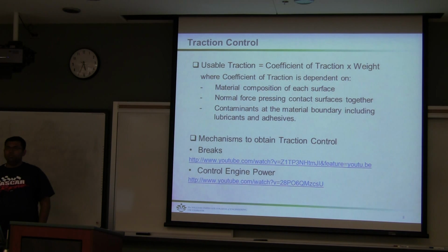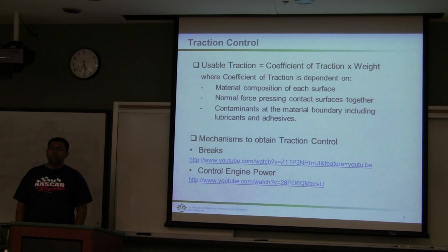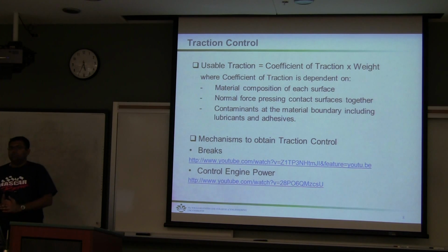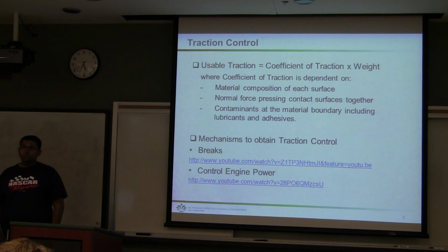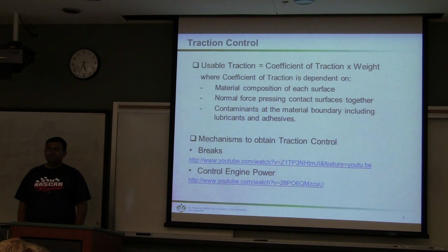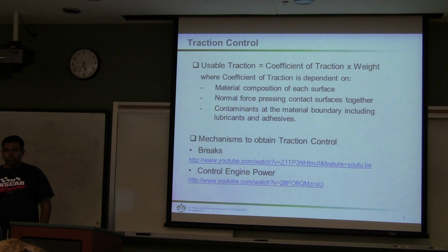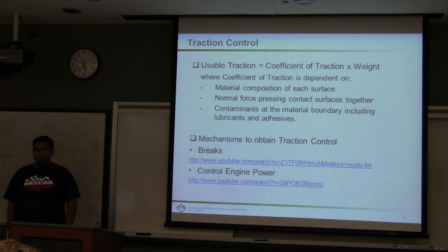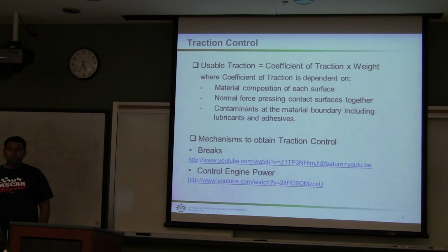There are some situations, and we'll see examples in little sumo robots or whatever, where you want the 360 like the one earlier. But in many cases, let's take an example, the flap of an airplane wing. You only want it to be up or down. You don't want it to rotate around and around and around, right? In cases where you only have a small range, you don't need as much torque because it's only got a limited range, and it could be smaller then. That's the advantage of a limited range one, they could be a lot smaller and a lot lighter.